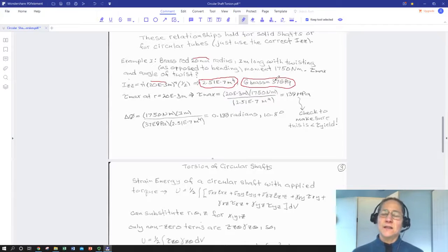So that's a little smaller than what I would expect for my tensile modulus. Usually shear modulus is a bit smaller. So if you're familiar with the E, the Young's modulus, being in the 70s, having a shear modulus in the 30s is probably pretty expected.